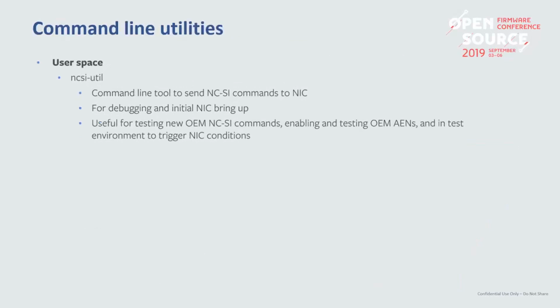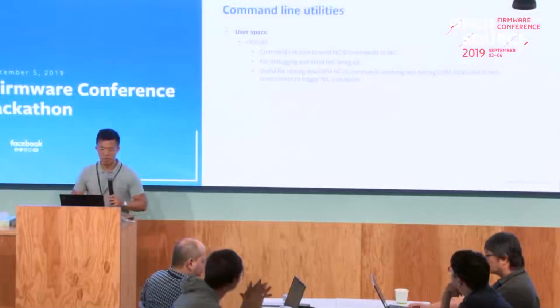For our purposes, we have a command line utility, NCSI-util. I introduced this a little bit yesterday; it allows the user to send any NCSI command or PLDM command to a device. We further extended this for PLDM update purposes. In addition to sending raw commands, it will recognize a PLDM package, parse it, and then do all the orchestration and upgrade. I'll show this in a few minutes.